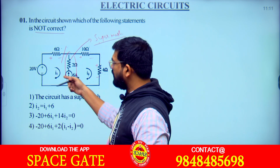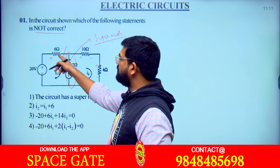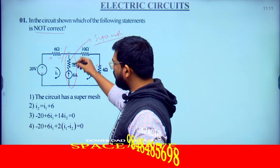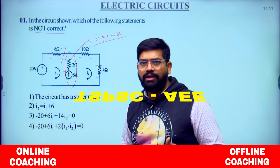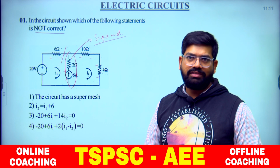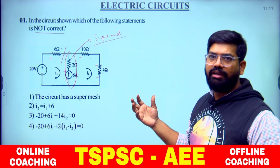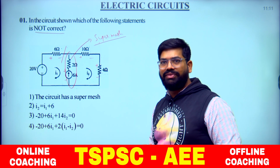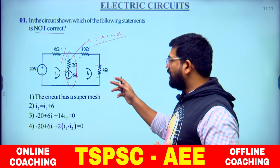So when current is entering the negative terminal, minus 20 plus 6 into I1, but what do we write for this? The voltage across this current source could be any value which we cannot say in advance. After finding all other branch voltages, then you can find that voltage, but in advance we cannot predict. That is the problem with this condition.